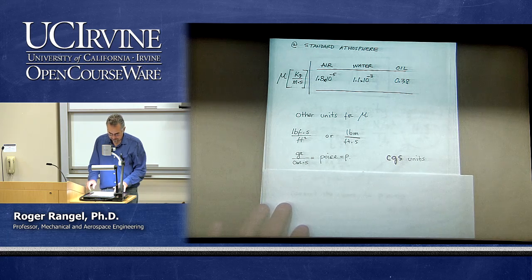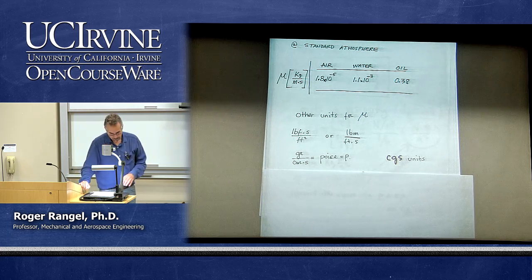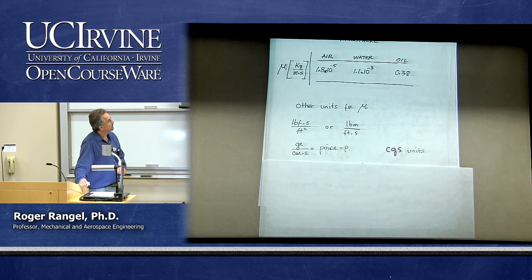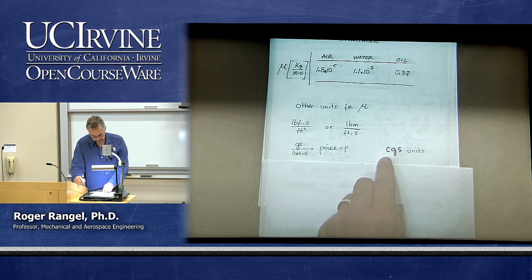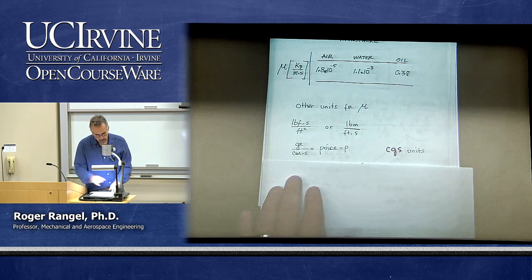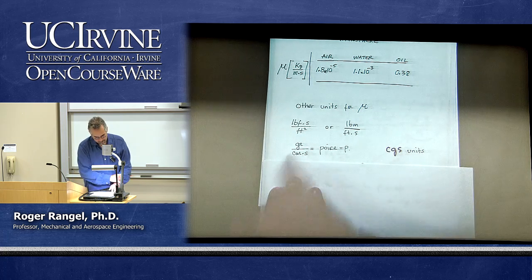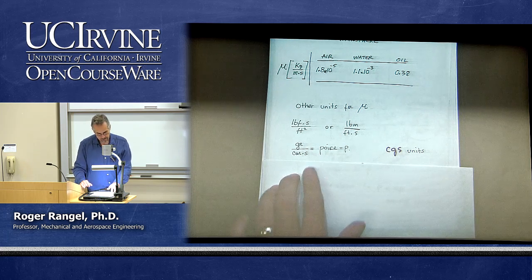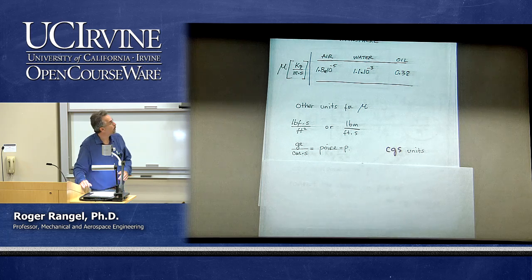that would be a unit of viscosity in British units. There is a historically important unit in the so-called CGS system. CGS stands, of course, for centimeter, gram, and second. So if you express the mass in grams, the length in centimeters, and the time still in seconds, so gram divided by centimeter and per second, that's called a poise.